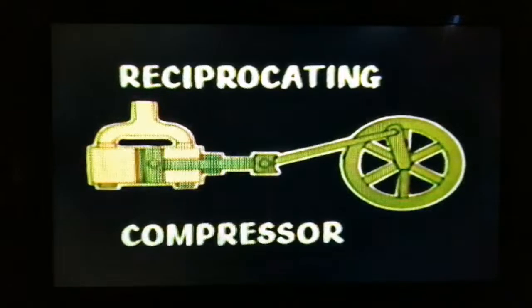A centrifugal compressor is one designed to deliver large quantities of air at low pressure, moved by centrifugal force generated by a rapidly revolving rotor. This type of compressor is being used more and more in power plants and will be discussed briefly. The greatest proportion of compressors used in power plants today are of the reciprocating type. This type will be discussed in greater detail.